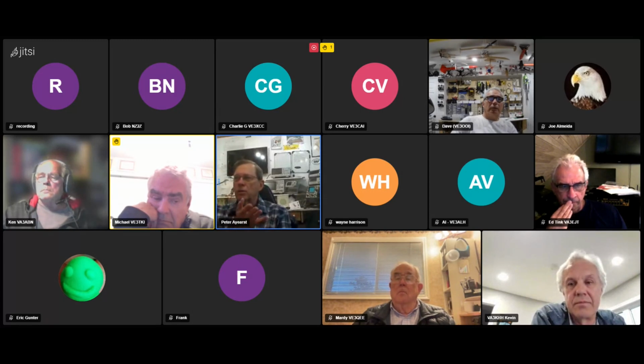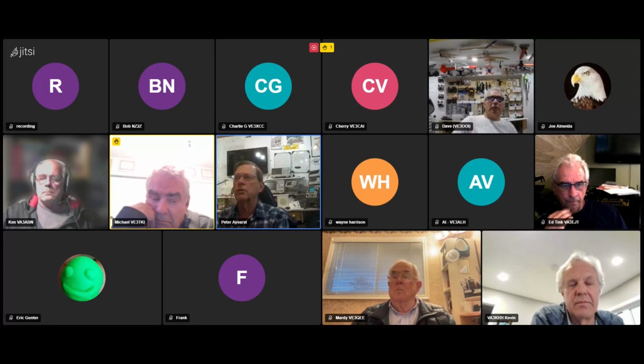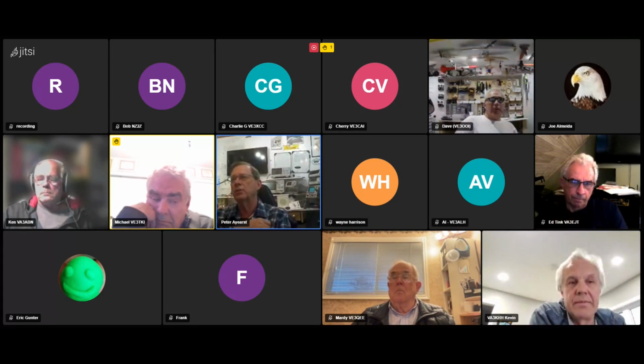When you're using your Spice log, you have to close it and open it up after every simulation that you do. With Phil's program, you can leave it open all the time, and as soon as you run your simulation, you click on the thing and refresh, and it's there. You don't have to open and close the error log each time. So one of these days, I'll demonstrate that one.